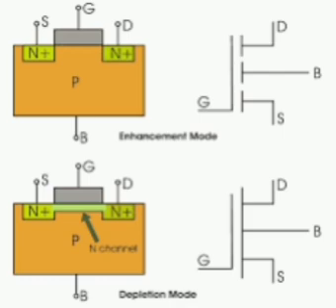It is a 2-terminal, 3-layer, single junction device. It is always operated under reverse biased condition. When the whole I region is covered by the depletion layer, it is called a swept out condition. In a PIN diode, if the whole I region is not swept out, then signal loss will occur. It is used in handling microwave power, as a microwave mixer, as a duplexer, in designing of transmit receive switch, and in designing of anti transmit receive switch.